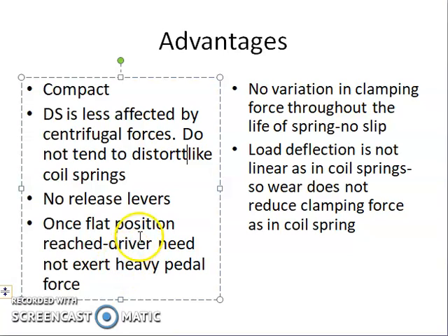Again, the diaphragm spring life is much longer compared to the coil spring. The clamping force of the spring remains the same throughout its life, and there is no slip. Since the load deflection is not linear as in the coil springs, even if wear comes, the clamping force will not be reduced.